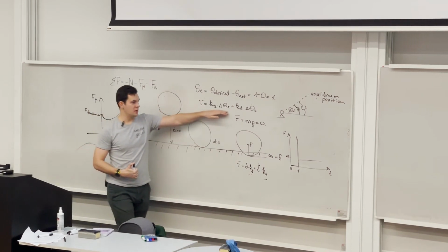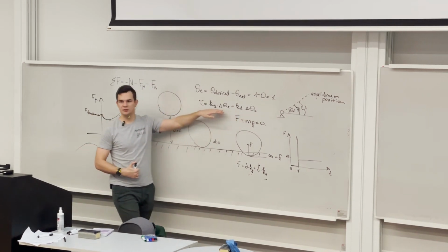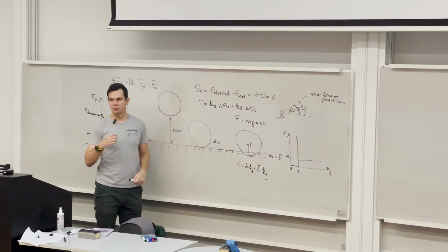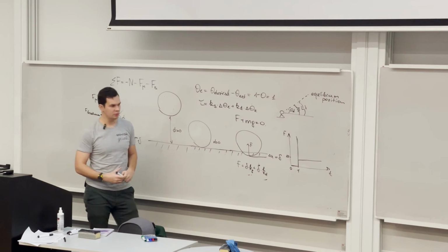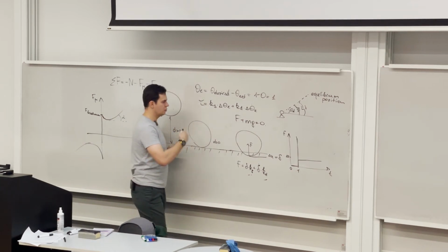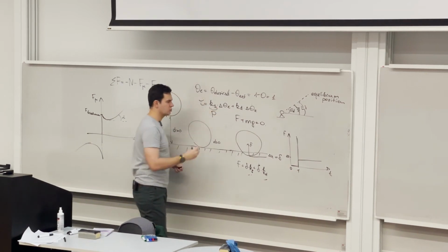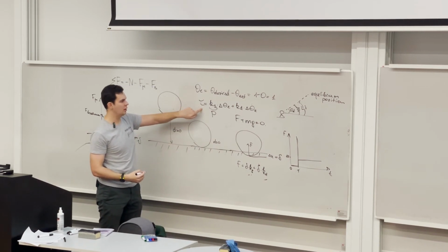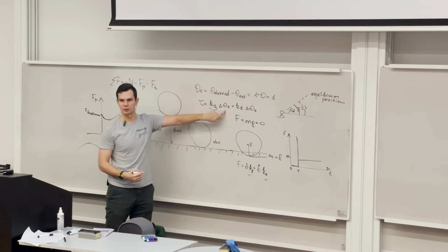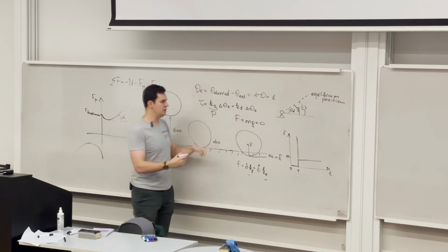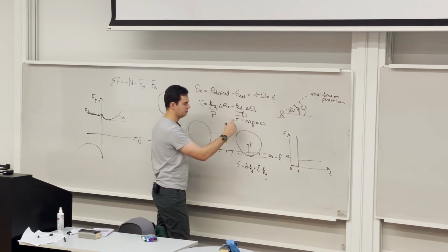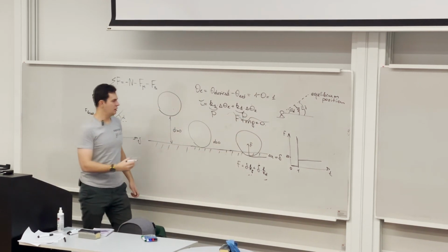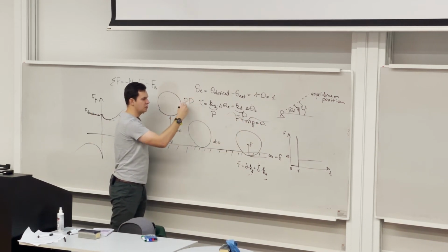And actually, this one is called PD control. PD, P stands for proportional. This is a proportional coefficient. Why is it called proportional? Because our torque is proportional to the error. It's a D because of derivative. And it's a physical analogy of the PD controller.